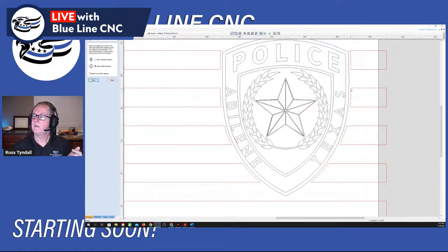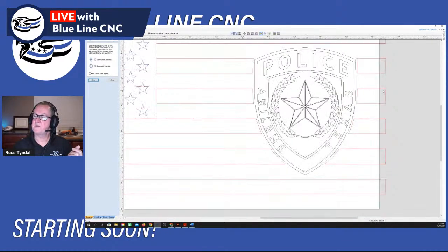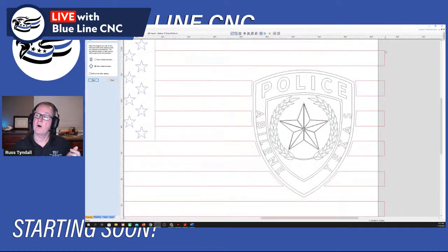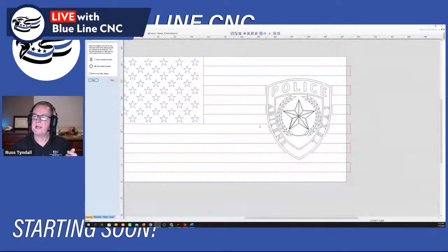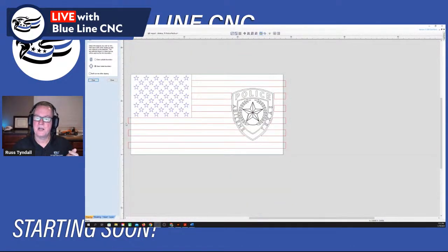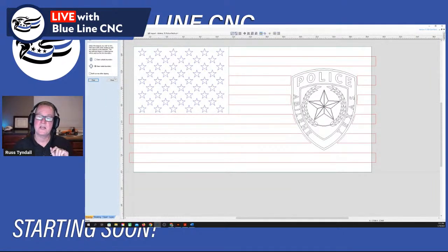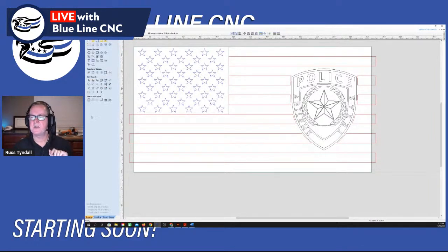And you can see what it does as far as our stripes, what we've designated, what we're going to designate to be carved out. They come up right to the stripe or to the patch, and they won't interfere with our design at all because we've taken that out of there. So that is how you bring in a patch, and how you use the offset function, and how you use the trim function within Vectric to go around your design and get it where you want it and get it perfect. So I'm going to close this trim objects. We don't need that anymore.